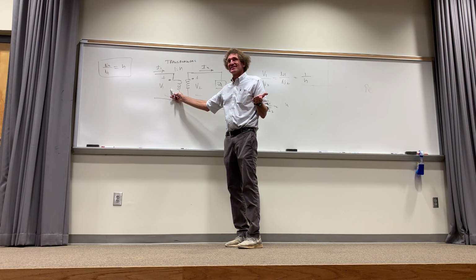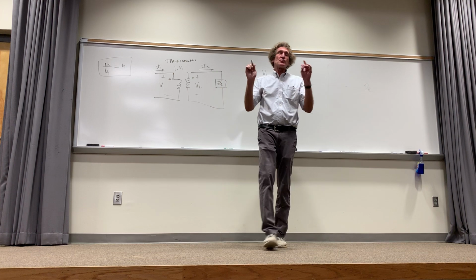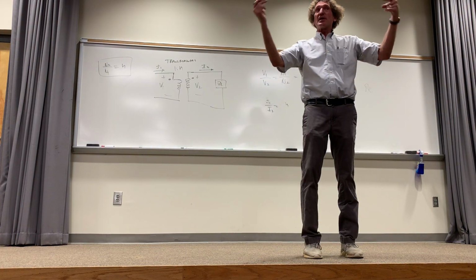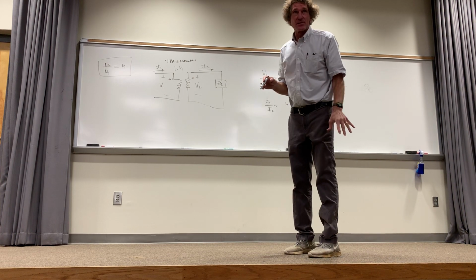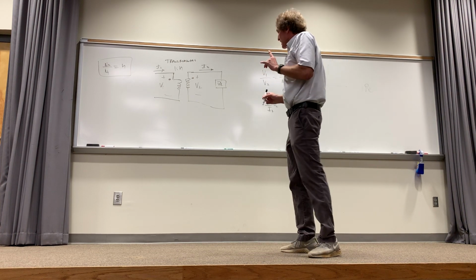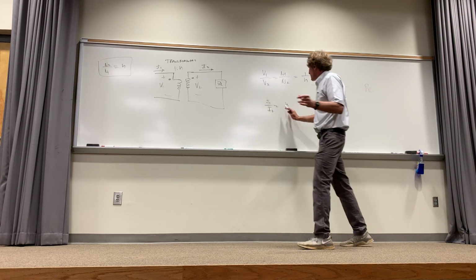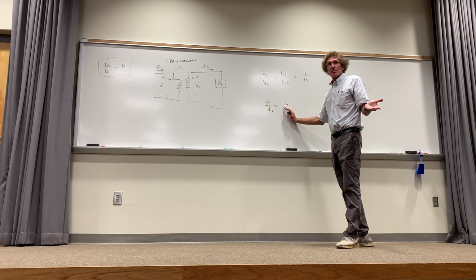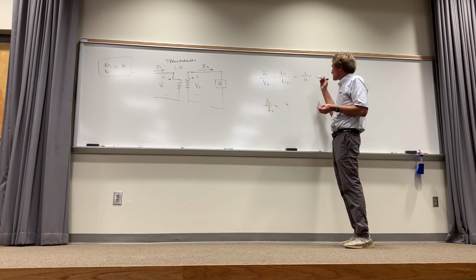So, in coupled circuits, we don't have the current going into the terminal. For transformers, it can be going out but still be positive. For mutual circuits, the current goes into the dots on both of them, all right? For transformers, unfortunately, this is his choosing. If the current was going in here, then this ratio would be negative. Do you follow me on that? They put a negative. I don't want to do that, and he didn't either. He left it positive. He just said this is going to be a positive ratio.